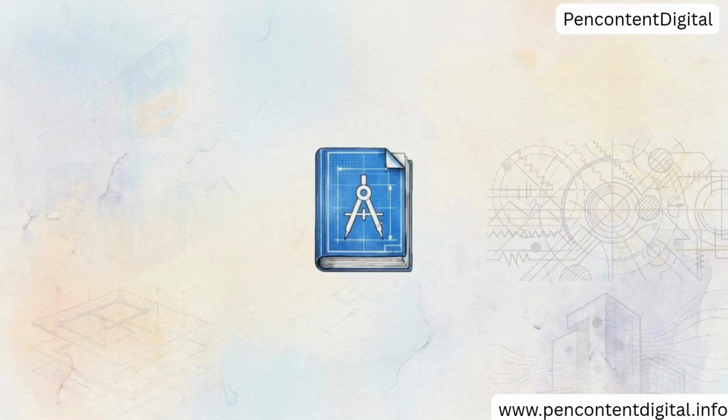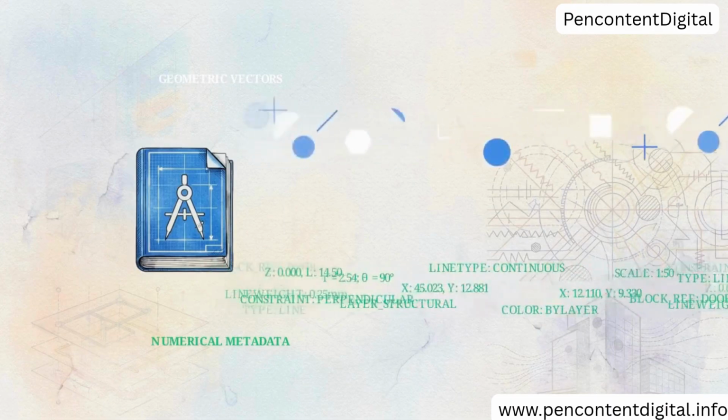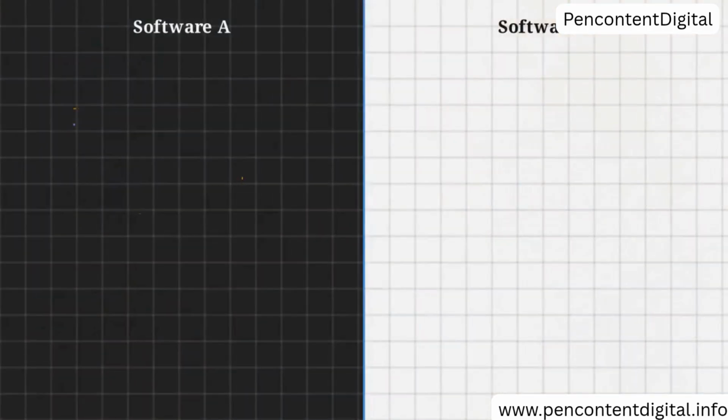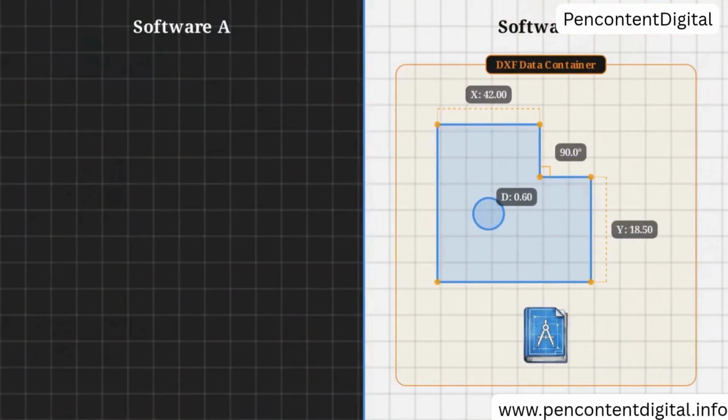DWG is AutoCAD's native repository. It stores both the visual geometric vectors and all the numerical metadata dictating how those vectors behave. When engineers share this data across competing software applications, they use a universal format called DXF. It translates the numerical constraints so other programs can read the file without corrupting the geometry.